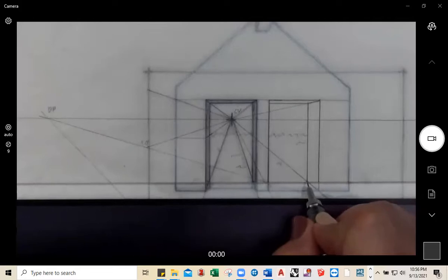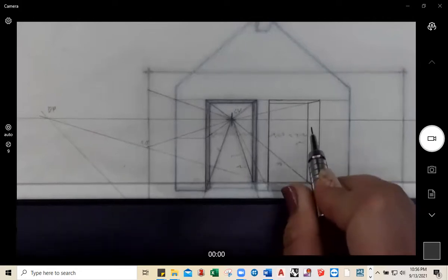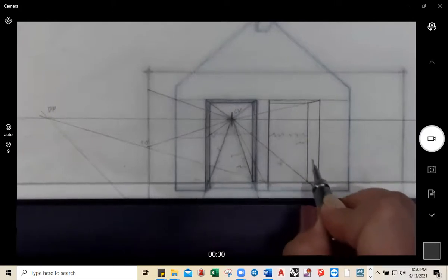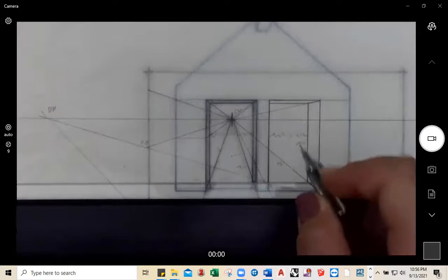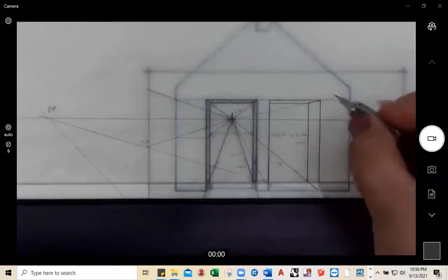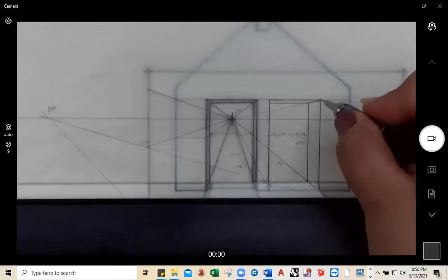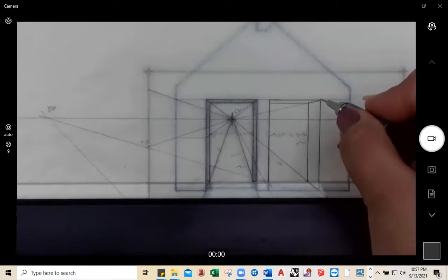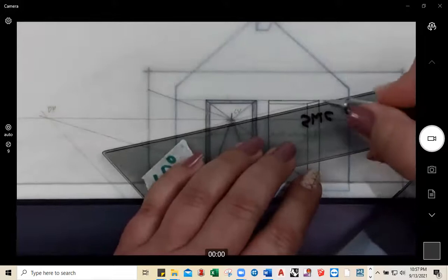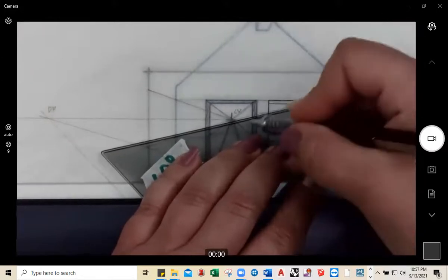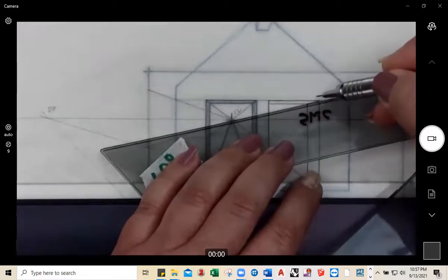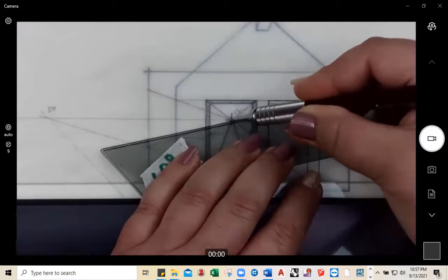That intersection, from that point, you're going to go up vertically, because that's the 2-foot depth of your wall. Now, how do you know where to stop? Well, from this intersection here of that opening that you created, this is the upper right-hand corner. You're drafting a line from that upper right-hand corner to the center of vision. So go ahead and draft up a line from this upper right-hand corner to your center of vision.